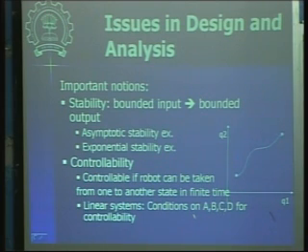There is another notion called observability, which we will see next. Observability basically refers to whether the sensors we are using are sufficient for our control purpose. So observability answers this question: with whatever feedback we are taking, are we able to construct the state completely out of that feedback?